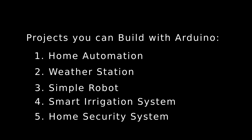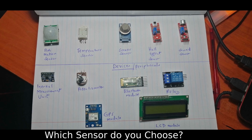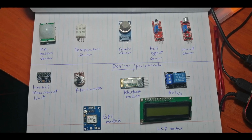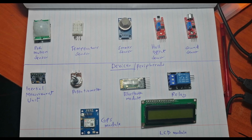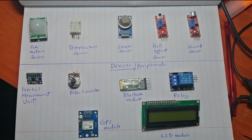Once you have a project to do, the first thing that you'll have to figure out is which sensors you are using. And of these sensors, which ones are inputs and which ones are outputs, because that's the first thing that you're going to have to configure in the Arduino void setup. You remember void setup.